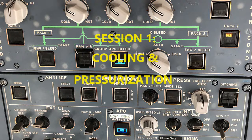Because you can have a vertical line that's amber. Okay, because the pack flow control valve is not closed, but it's also not in agreement with its corresponding push button. So when you have that disagreement, that vertical line is going to illuminate in an amber color. The green vertical line is just indicating that it's not closed. But then you have a green horizontal line, that means it's completely closed. Okay, it's completely closed, green horizontal line.